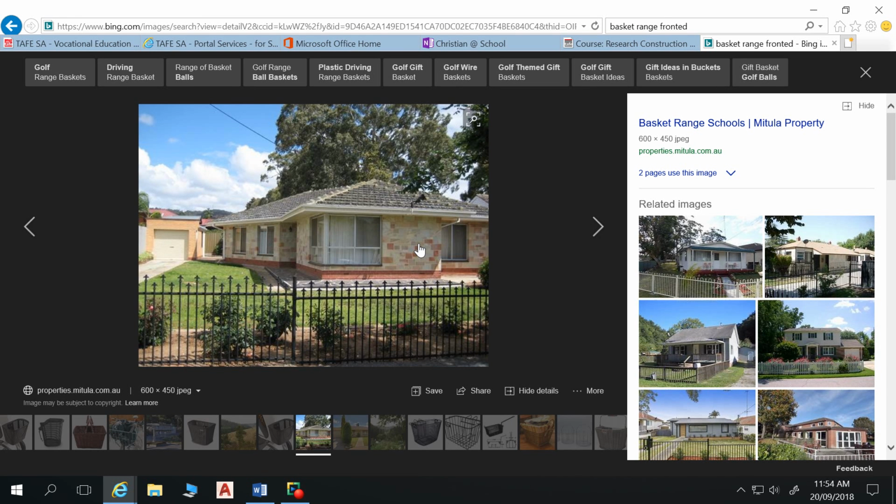You've got one at Sellick Hill. You've got one just off Gorge Road, where they mine basically just for aggregate, for concrete as well. So that might be bluestone also. There are various different types of stone suitable for aggregates as well. But yeah, you've also got granite mined. So granite gets used in bench tops and things like that. Trying to think of other stones. I think we've pretty much covered the stones in South Australia that are used in construction.